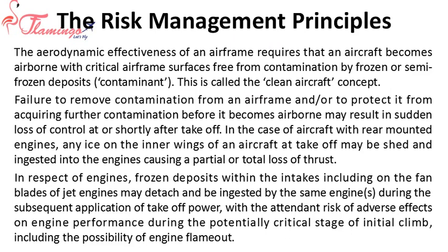The aerodynamic effectiveness of an airframe requires that an aircraft becomes airborne with critical airframe surfaces free from contamination by frozen or semi-frozen deposits, contaminant. This is called the clean aircraft concept. Failure to remove contamination from an airframe and/or to protect it from acquiring further contamination before it becomes airborne may result in sudden loss of control at or shortly after takeoff.